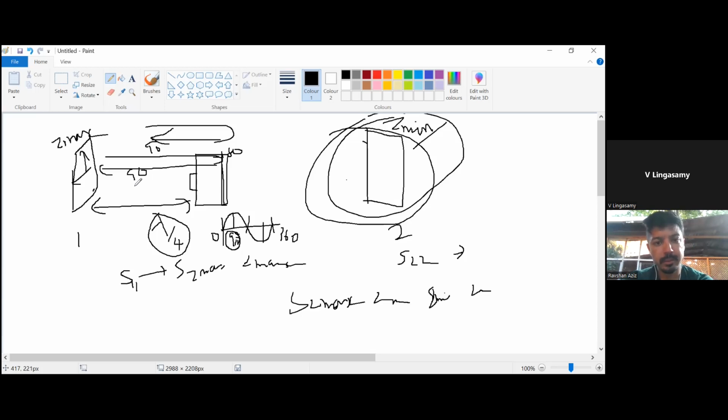So, distance to reference plane. Which means, this is the port where I have to estimate the phase, wherever I choose to estimate it, here or here. That is the distance to reference plane. For example, we can again keep it as lambda by 4, which will fall exactly here. While I'm sending the signal, it gets reflected back. Here I'm just evaluating how much phase this unit cell is generating. That is what I can expect.